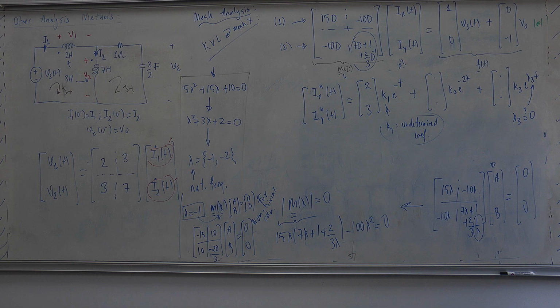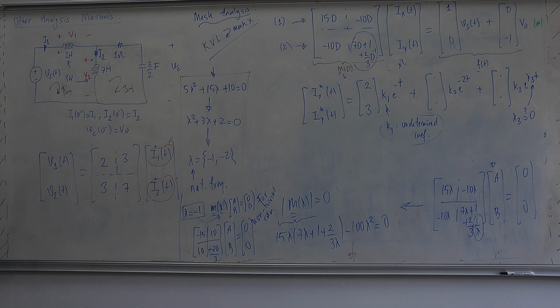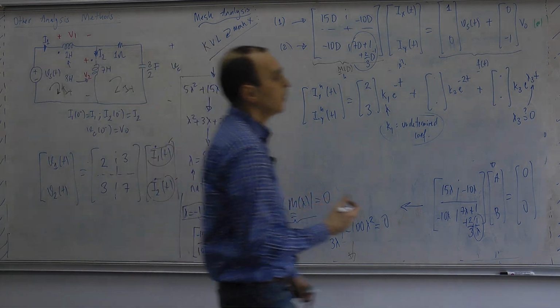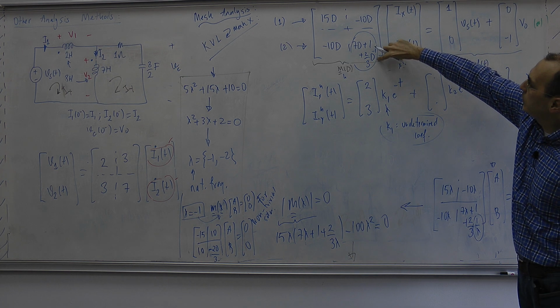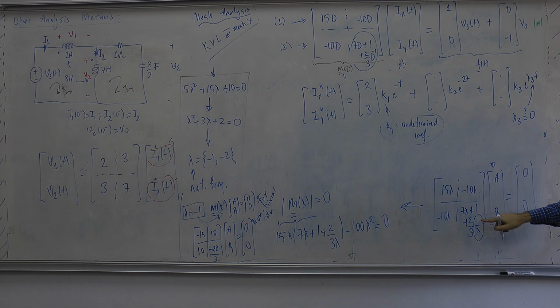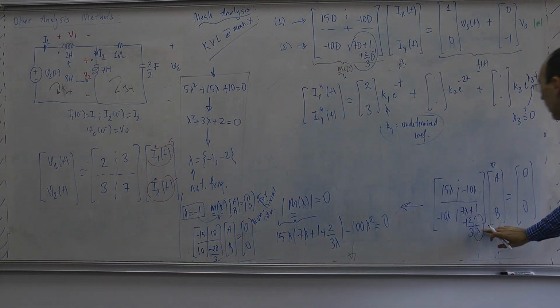And that third natural frequency, we are not sure about it right now. Is it equal to 0? Well, at the beginning, by the visual inspection of this circuit, we have said that this is a third order circuit, so we are actually sure about it. There should be a third natural frequency. So in mesh analysis, due to the presence of D inverse operators and related 1 over lambdas over here, you are not allowed to insert lambda is equal to 0 in this calculation.